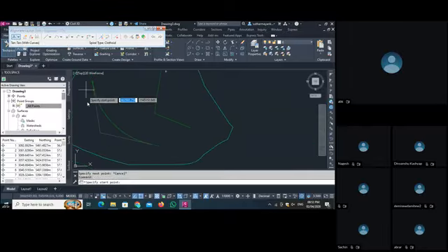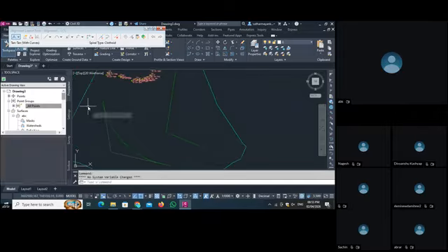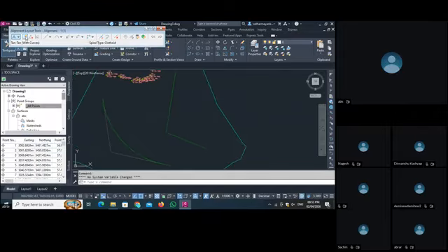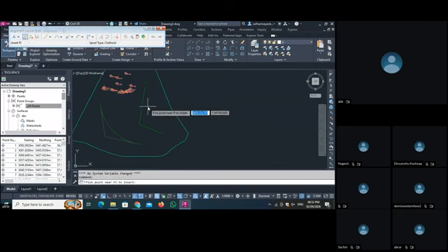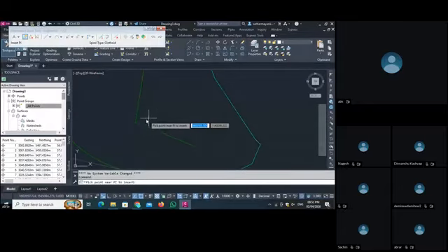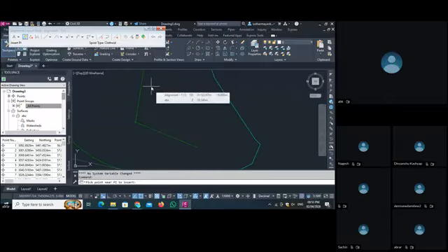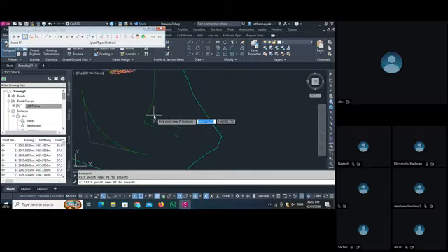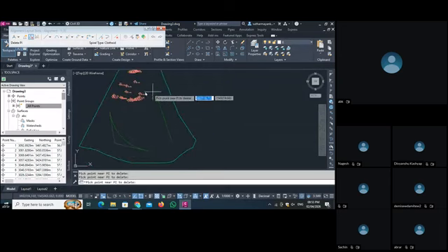Now, if I created these things, the second thing is the PI points. If I select any line and I understand that this is not our proper line, this PI point is not there. This will be straight. So if I select one PI point here, it will set the alignment edge per my PI point. If I select the delete PI, whatever PI I select, it deletes automatically. See, now my alignment is straight.